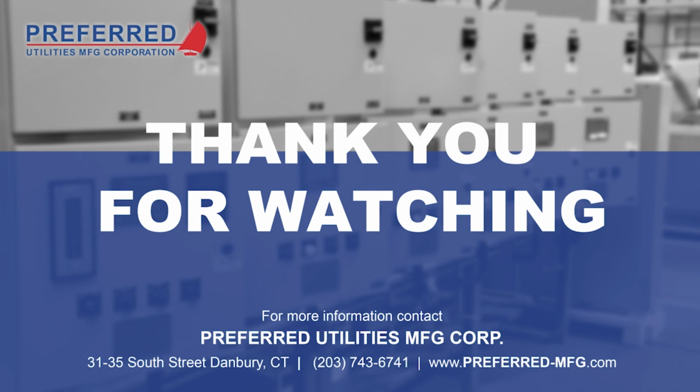And there's ways of really correcting that. The most simple way people have used in the past has been orifice plates that you put in front of the scanner itself. The orifice plate being a small pinhole, so you don't have full view. And that actually works quite well in a lot of applications. Now, obviously, there's other ways of doing it. There's what we call filtered glass, if you will, or quartz for like UV.